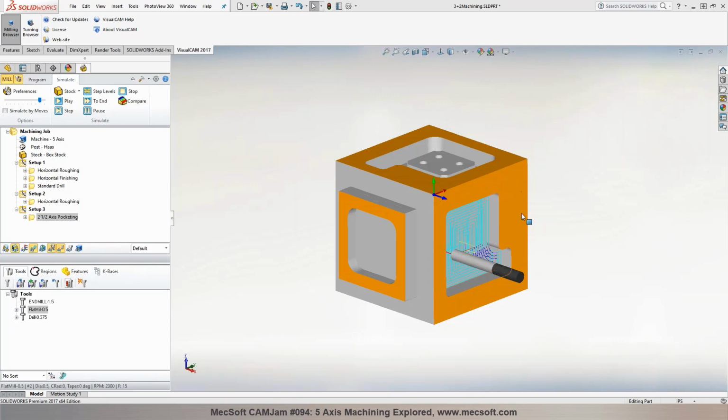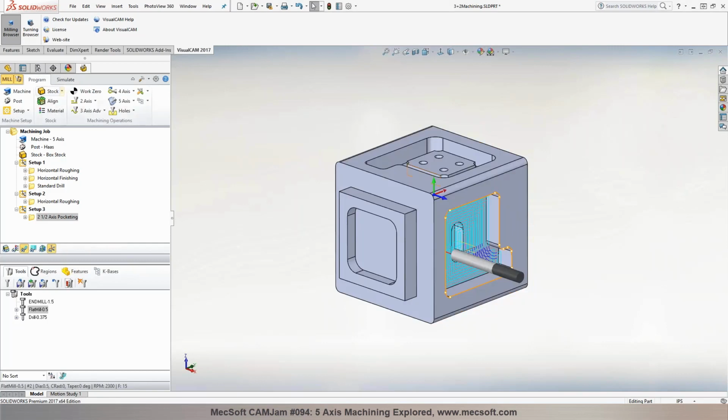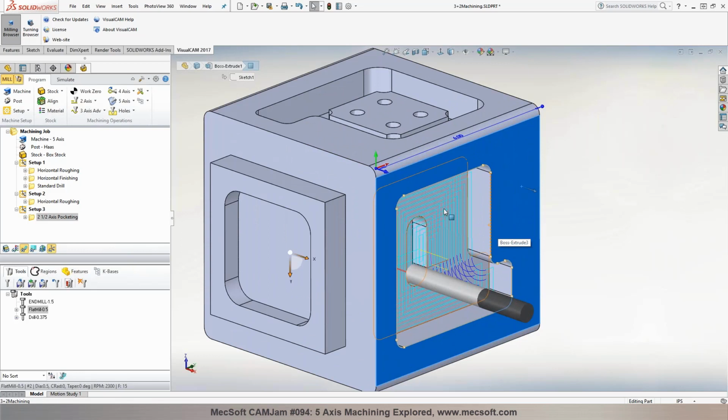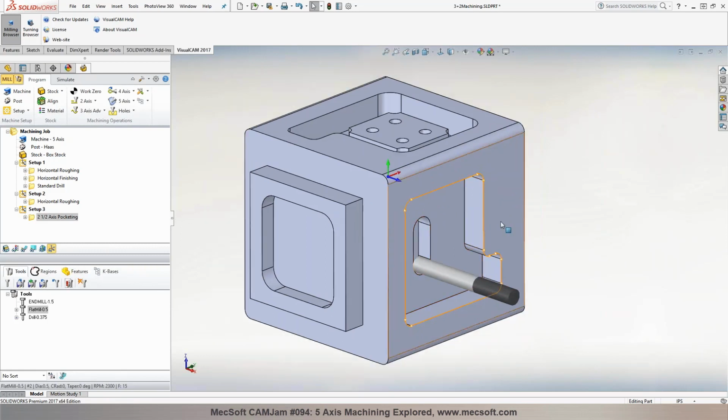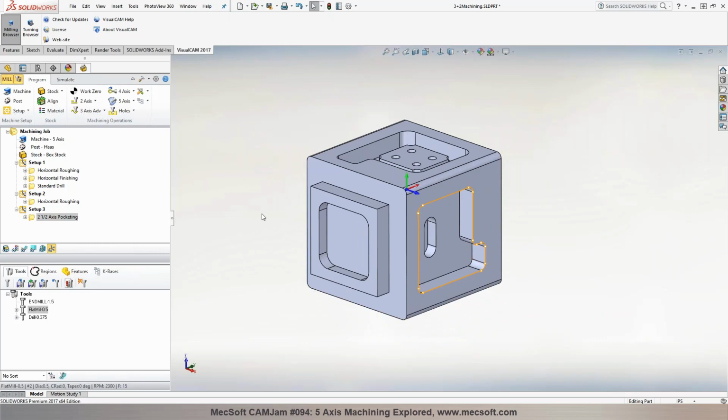You would still be setting the z-axis normal to this particular surface, but then you would program a 3-axis roughing and finishing toolpath rather than using a 2-axis operation, since the floor of the part is not planar. If it's at an angle, not planar with the orientation, you would basically have to program it with a 3-axis toolpath. Yes, that will work better. I understand. I'm sorry.